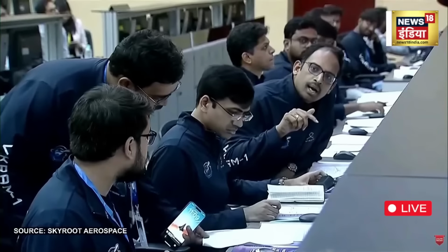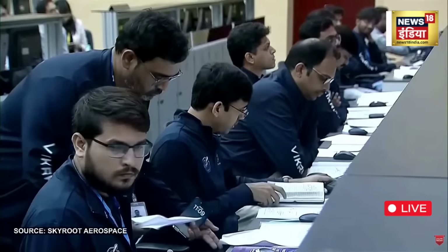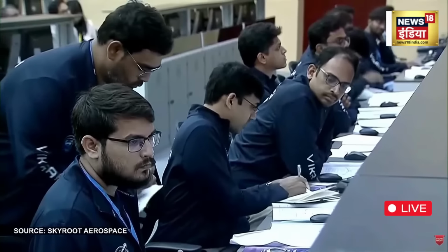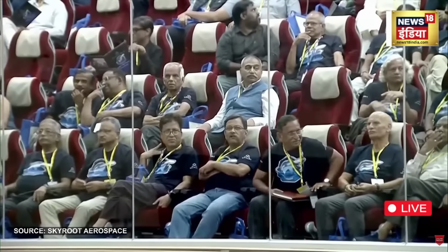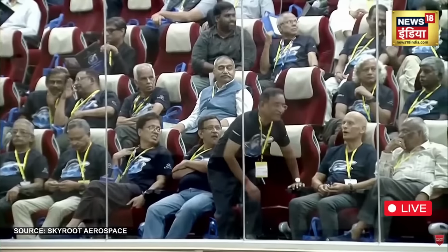And all those liquid engines are powered by hypergolic propellants, right, Suyesh? Yeah, that's right. So we use something known as MMH and N2O4. These are 2 chemicals. They're stored in separate tanks. And the way they work is when you bring them in close proximity to each other, they spontaneously combust. Of course, you need a certain threshold concentration. The whole advantage is then you don't need an ignition system. So you've deleted a potential failure point out of the system. So it's kind of unique and useful as well.